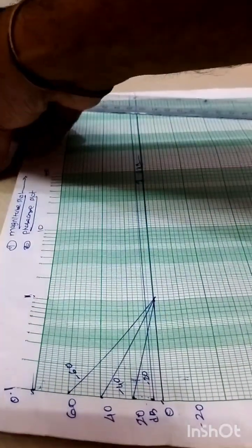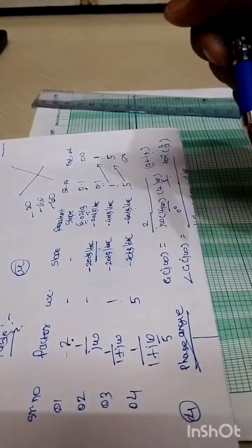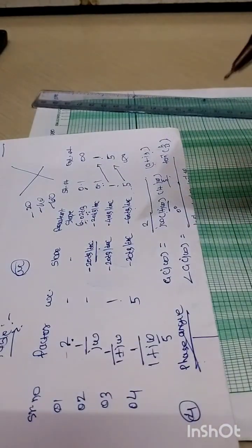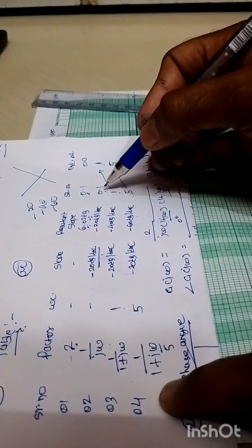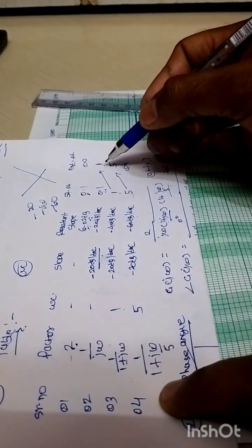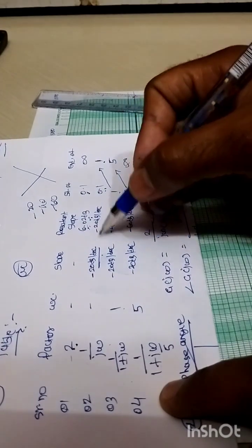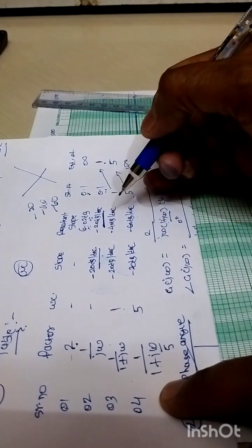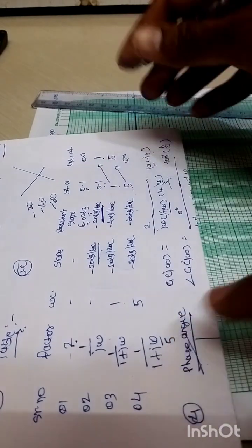So one more time, when we consider this table for the magnitude plot, this factor 1 over j omega has what starting point? 0.1, and it ends at 1 radian per second, whose resultant slope is exactly equal to minus 20 dB per decade, right?